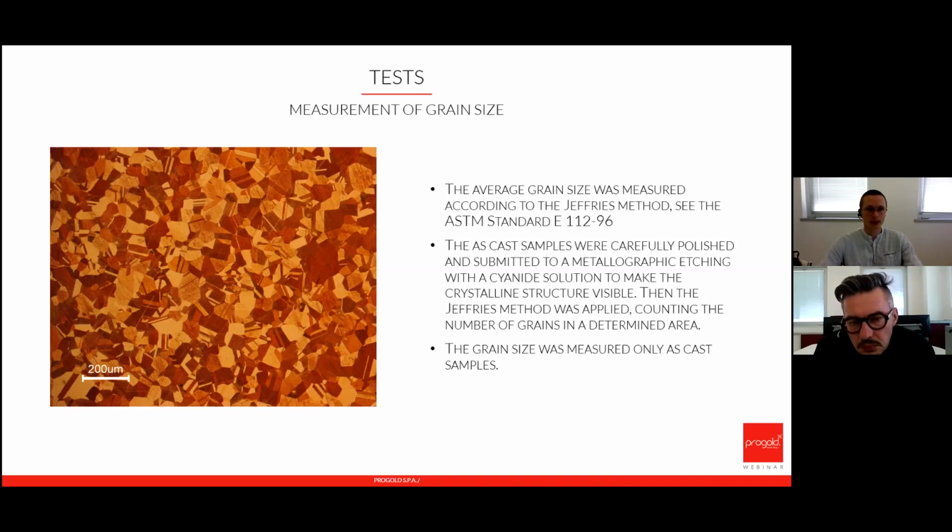For example, in the case of zinc, we know that zinc for casting is not good, but as we said, for drawability it is excellent. And if you are able to accept some compromises on the alloy, there are some elements that could help the form filling and the viscosity of the alloy. But first of all, I will answer that the most important parameter for filling is the temperature.